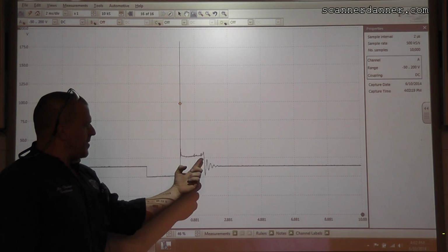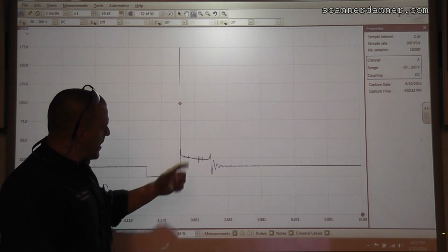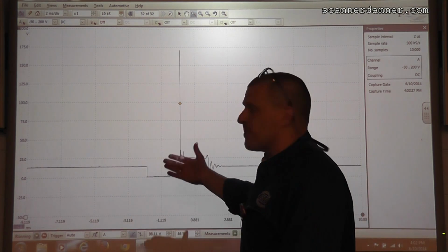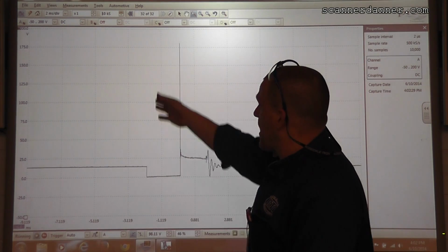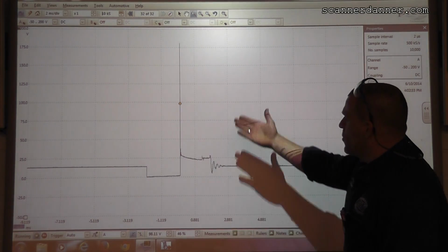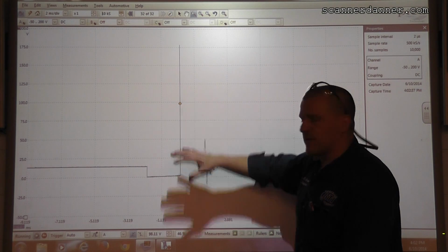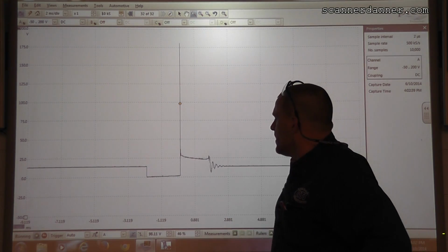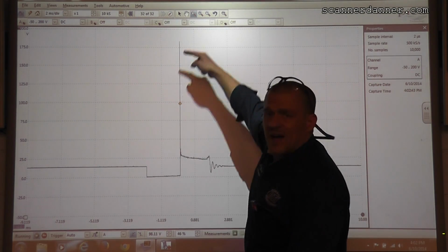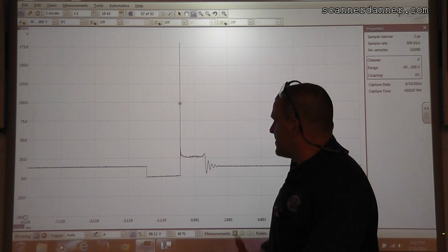Yeah, we're missing some of that in there. Some of those really fast events, maybe. Still, here's the point. It's pretty good, isn't it? This is a pretty good sample rate for this small time base. So if you wanted to snap the throttle and watch it here over and over again with this trigger, that's fine. The only problem with snapping the throttle on ignition events, this trigger line changes. If this is where your trigger is, you may miss some of the events.